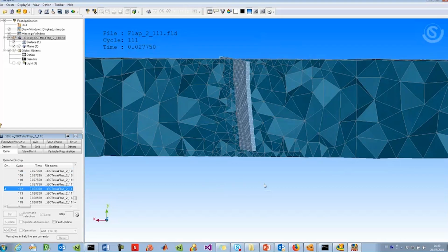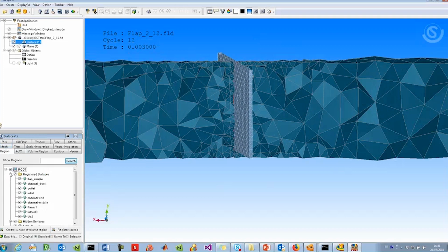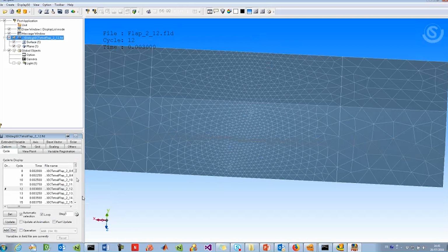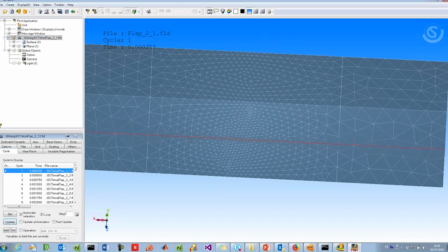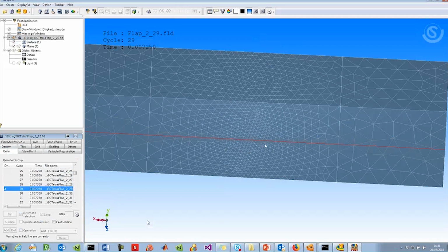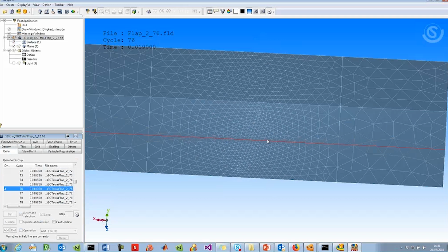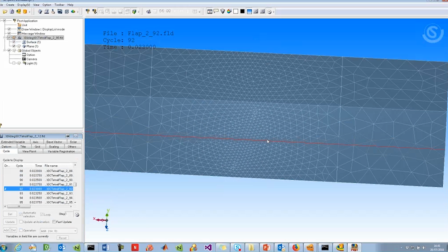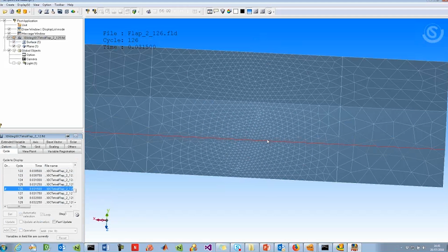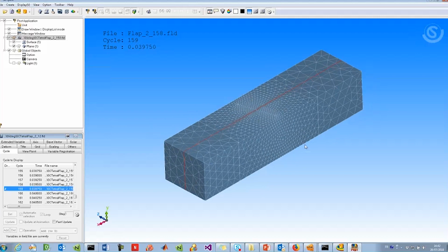And this is really, really interesting, because if I do something like that, the phase, region, and everything, we can even see what happens in all the surfaces in which we have put different constraints. We can see how the nodes can glide in this direction, both directions here, and that constraint on the others, and this really helps guide the CFD deformation. So it is really interesting. For any surface that you have defined in this CFD model, you can define different constraints, so you can really help avoid as much as we can negative volume problems. So for this example, I am pretty okay.